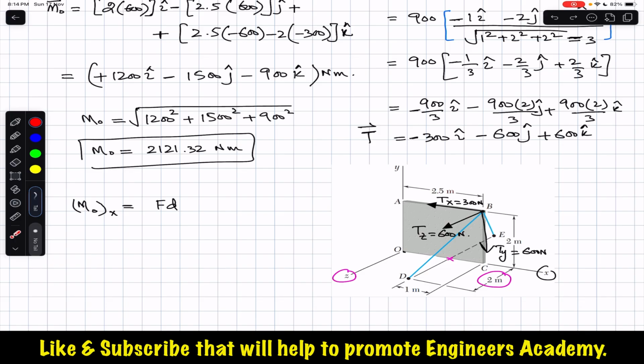Similarly, the y component is intersecting with the x-axis. So this means that the perpendicular distance between the y component and the x-axis is 0. So it's not going to produce the moment about the x-axis since it is intersecting with the x-axis. So this component cannot produce the moment about the x-axis. Only the z component is going to rotate this concrete wall portion.